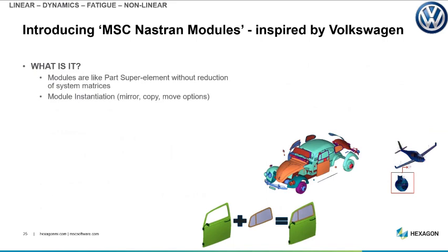And then a feature that's relatively recent and I think is underutilized by a lot of people is the concept of a module. If you ever used or know vaguely what a superelement is, it makes it kind of hard to understand, because at first glance it sounds like it's the same thing. It's not. So if you look at modules, it's simply a group of elements with its properties and everything, and I consider that the sub. But the advantage of this is I can now mirror this, not by physically moving the nodes. I simply say, well, I want a mirrored copy of that at that location.